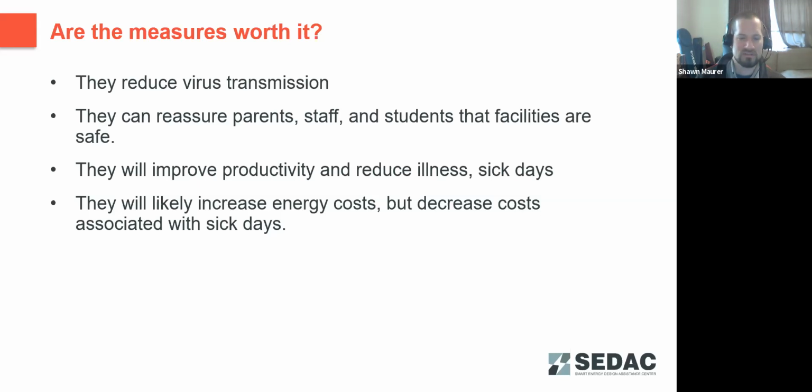And the last question, looks like most people got this. A window fan exhausting to outside is the best way to ensure clean air delivery. Just to comment on these briefly, the MERV 8 filtration, again, isn't filtering air for the space. It's filtering air for the operation of the mechanical system, to keep the coils and the fan clean. An in-room air purifier under a return vent is going to take that purified air and exhaust it straight out of the space. So it's not going to dilute air in the space effectively.